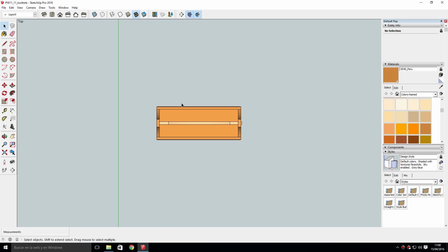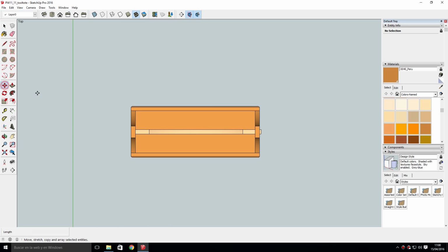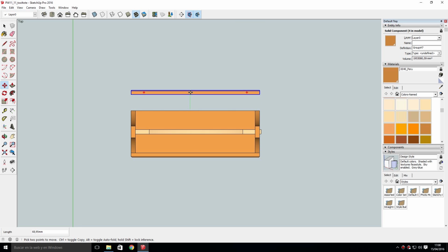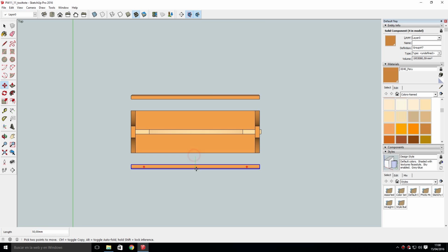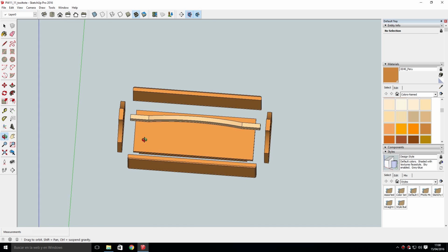Select the top view and parallel perspective to make the work and understanding of the step to perform easier. Again, with the Move tool, displace 50 mm all the parts. Once they're selected, you can enter the distance with the keyboard and press Enter to get the desired position.